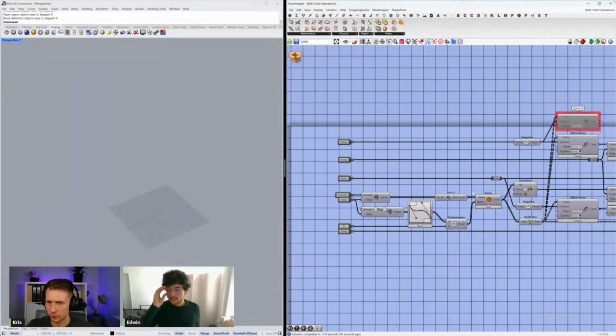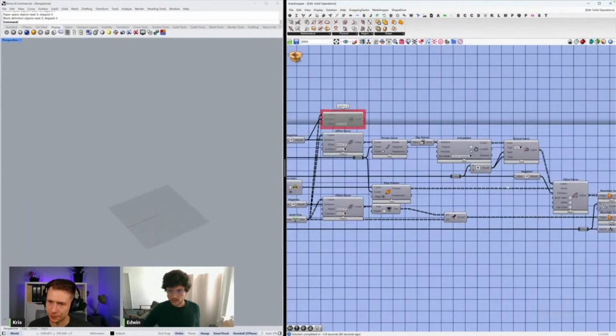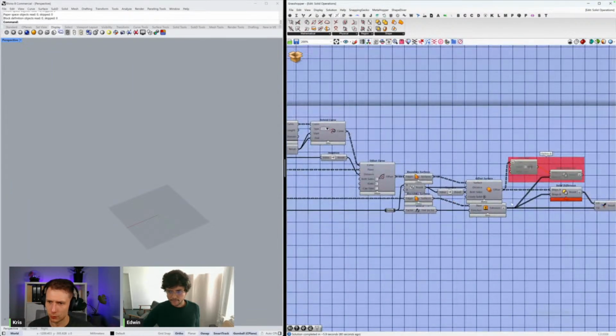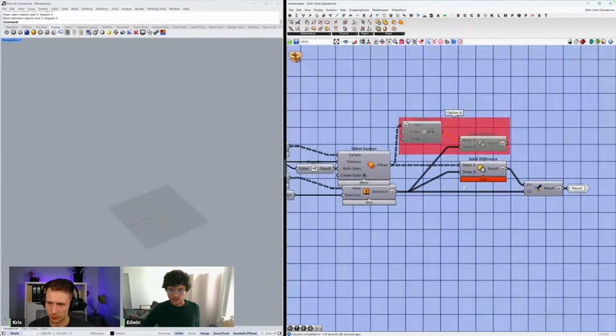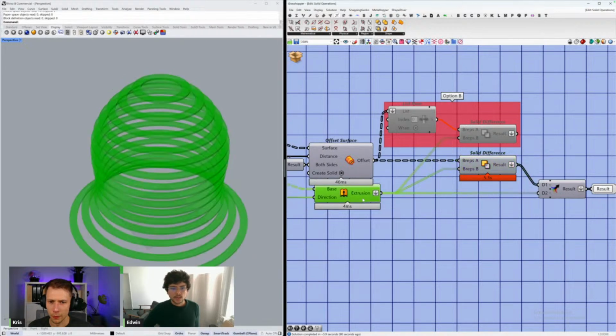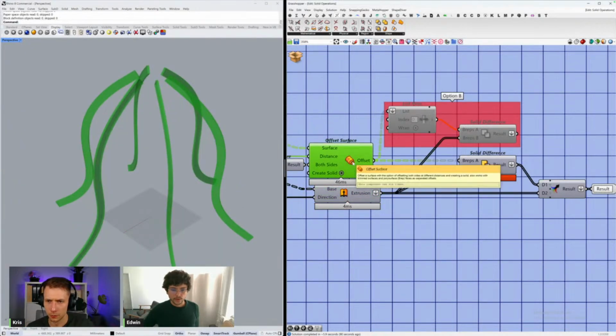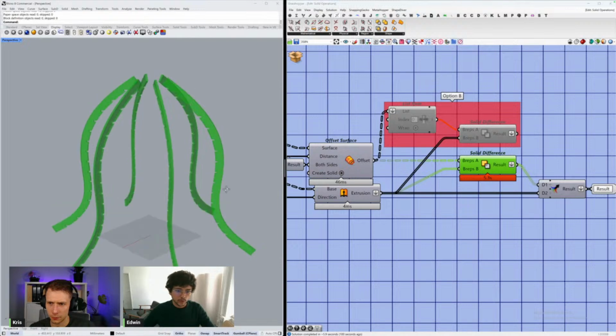I will be saying some small tips here and there as well. The main one that we are focusing on here is the solid difference. Here you can see that's of course what is taking the majority of the time, 5.3 seconds. What I'm doing is I have these circular elements, and then I'm doing a difference with the ribs, so that we can end up with the notches.